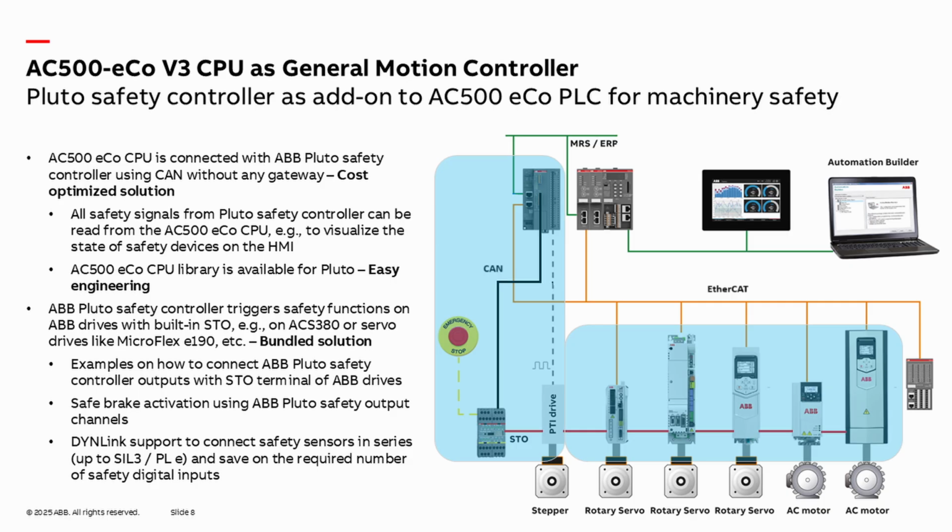And with this bundled solution, you can trigger STO on all the drives with STO support, including servo drives supporting STO, safe torque off. The drives which don't support STO, for example, some servo drives we have today, then you have to use contactors to de-energize the drive side or motor side or both, depending on your application, to reach a safe state with that drive. Even though I shall mention that also our servo drives, of course, in the next steps will get STO on board.